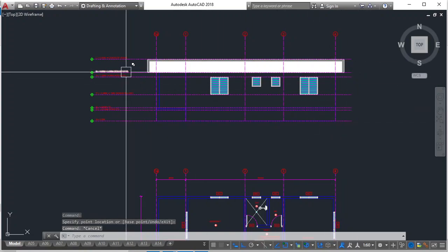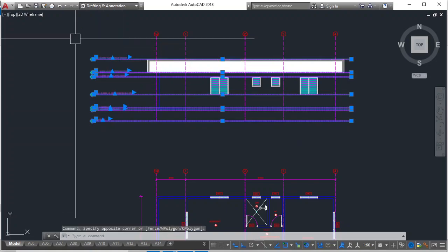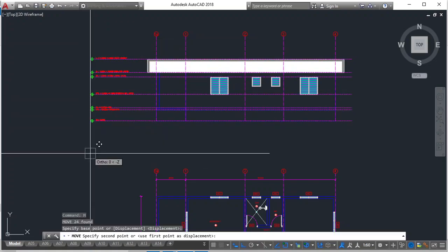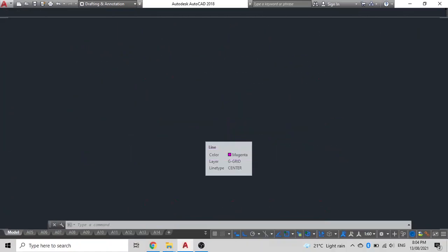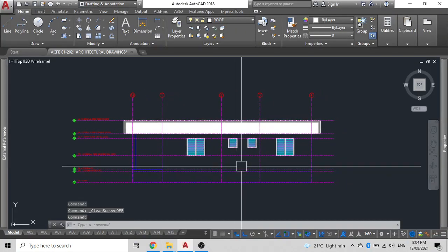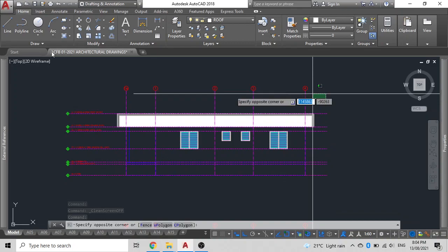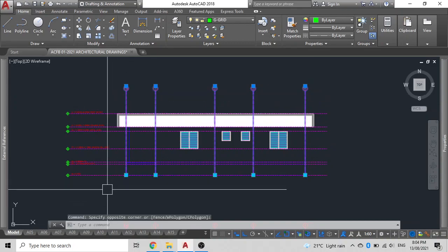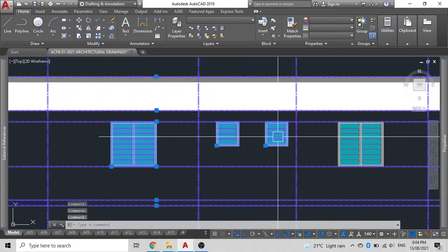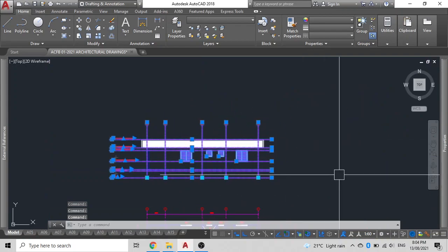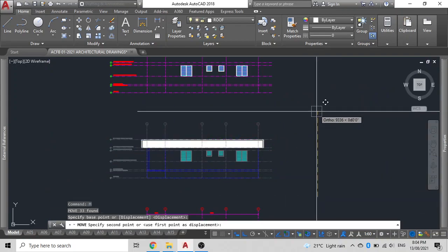And since this looks to be a bit inconsistent with this one, what I'll do is simply select this over here and move this out slightly so that both the sides look neat and consistent, like so. Now what I'll do is select this as well, select all my windows and move them up at a distance temporarily. So I'll use 10,000 millimeters of spacing between the actual size.